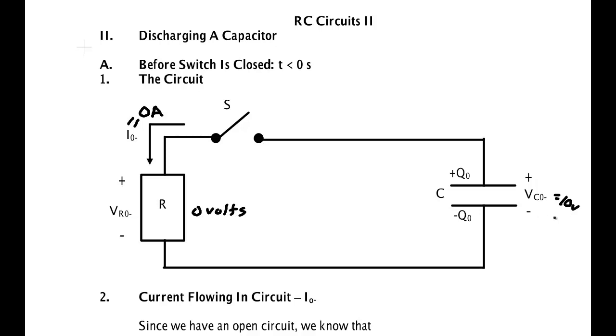But there is some voltage, whatever that is, right now across that capacitor, and that means that as I go around this circuit, that voltage has to be dropped somewhere. It's dropped across this switch. So right now that would be 10 volts, for instance, if that's what my capacitor was charged to. So again, the open switch is where you can get shocked.